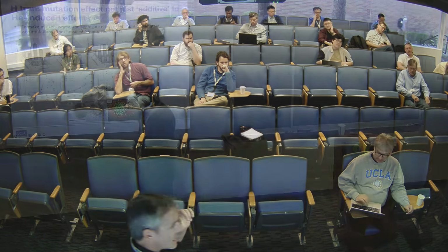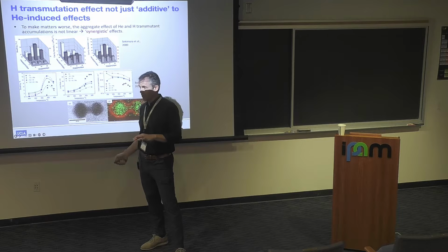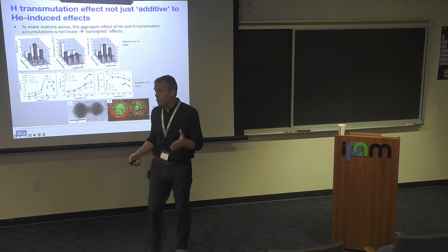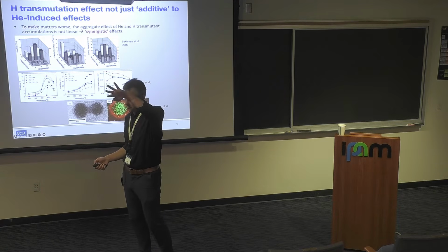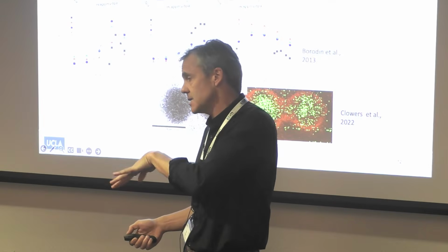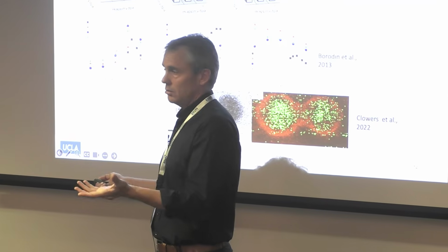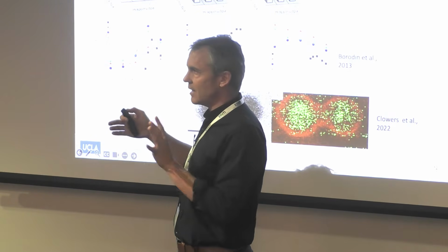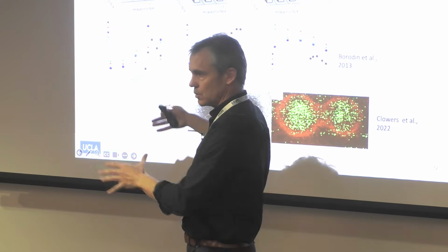But we have been trying, as I said in the beginning, to push for a materials testing facility, which will not be a fusion reactor, but will be a surrogate. These surrogates almost always have neutron energies higher than 20 MeV. They have a high energy tail that decays fast, and you could say, okay, we're not going to have that in fusion, so we don't need to worry about it. But what we do is we test and validate the models against those surrogate facilities, and then we bring them over. So we need to make sure that we capture what's going on in there.